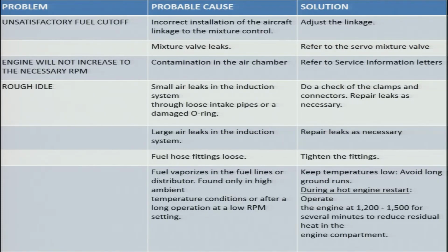Another reason for unsatisfactory fuel cutoff might be that the mixture valve is leaking. In that case, we need to see if we can fix the leakage problem. If not, then we have to replace the parts as per the manufacturer's guidelines.